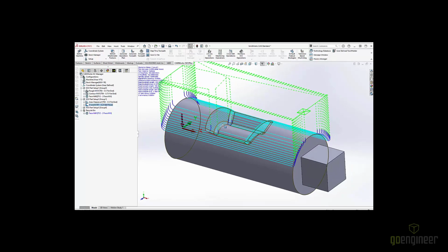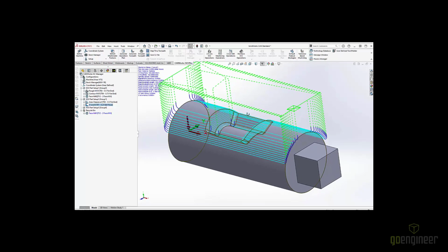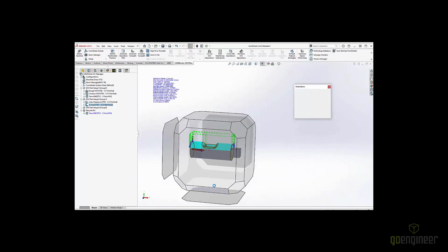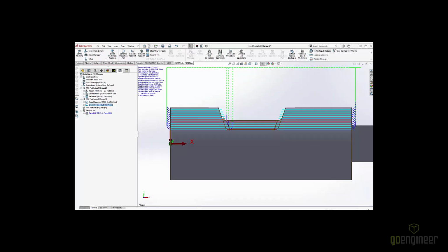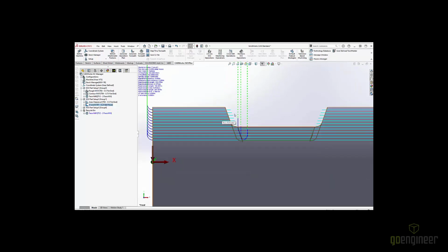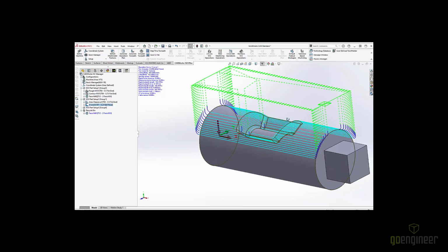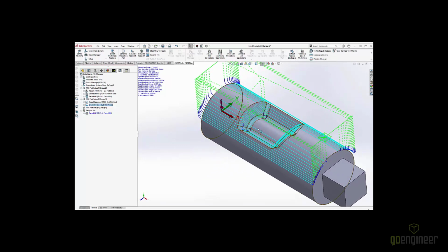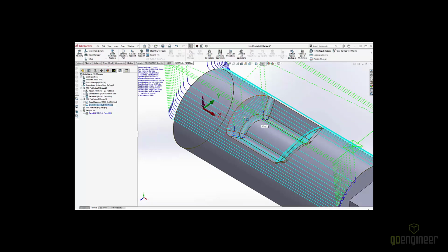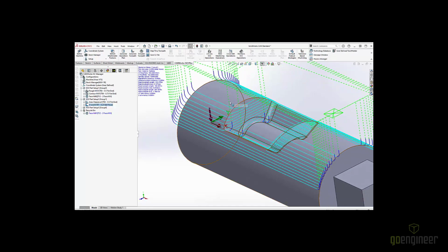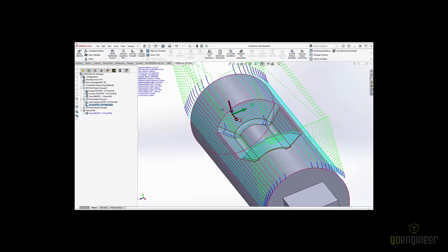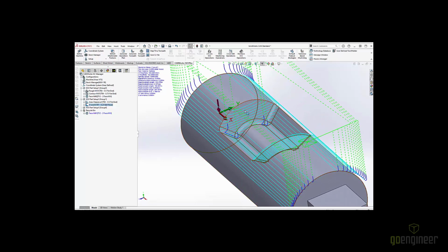The only finishing pass we have available, as I mentioned earlier, is the Z level. It's pretty easy to understand how this works if we take a side perspective view. We're slicing the part with different Z planes. Where those planes intersect our surfaces, we're creating toolpaths. So this gets a pretty good surface finish in most areas, but in certain flat areas, it can tend to break down.